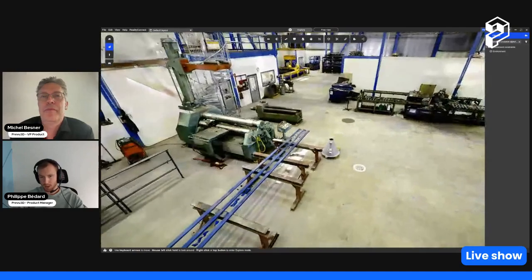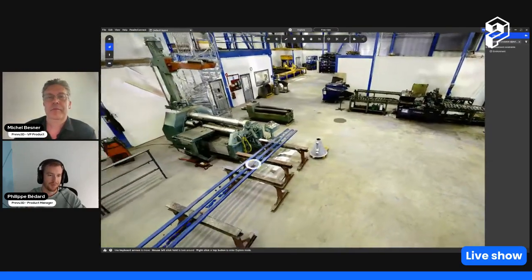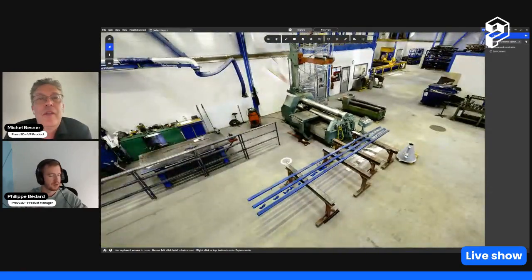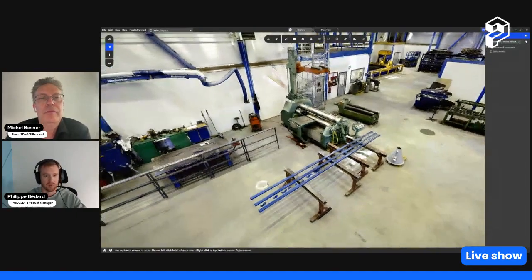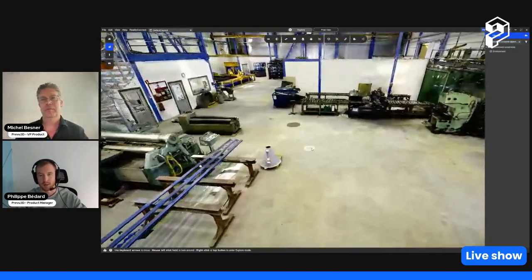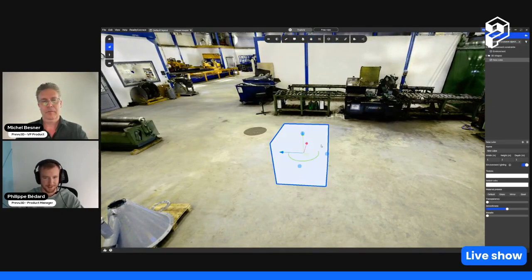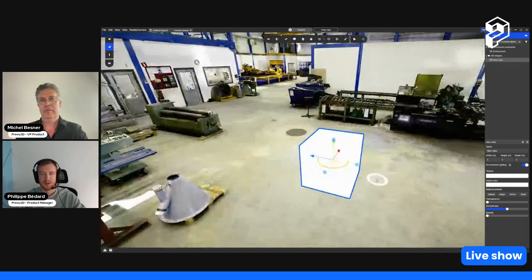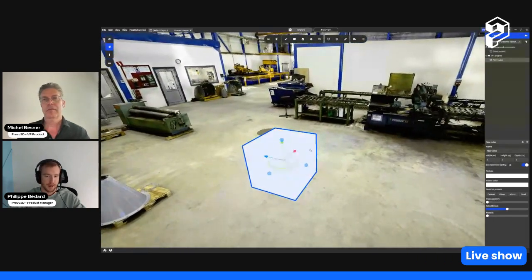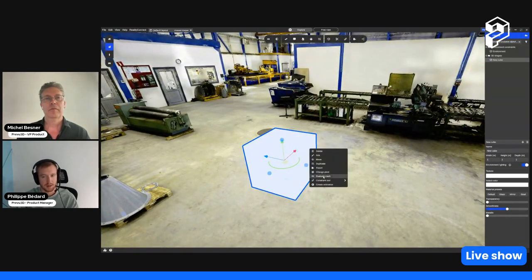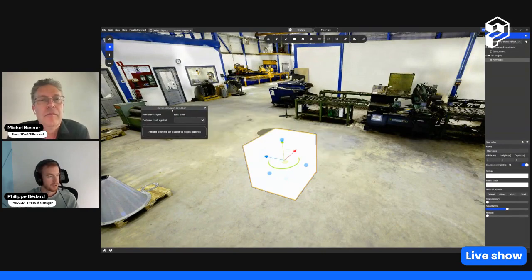Yeah, so I can maybe show you a quick example first with a cube, and then go through a more advanced workflow to show you exactly how it can be used. Let's start with a simple cube. We can right-click on the object, enable the Evaluate Clash tool, and decide against what it should be evaluated.